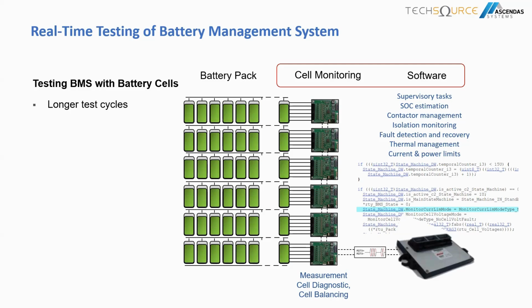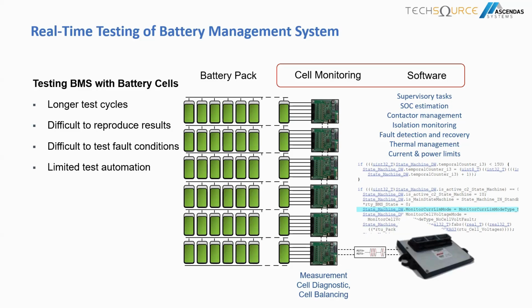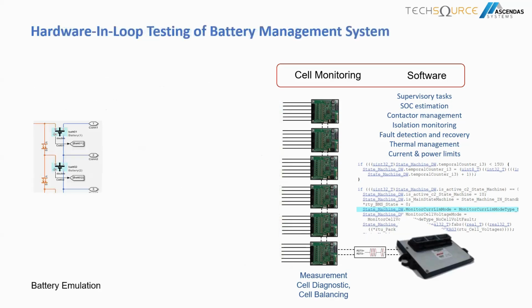These are just some examples, because it's difficult to do testing with actual battery systems. Especially for fault diagnostics, we usually use real-time systems to develop our implementation. One example of a real-time system is Speedgoat hardware, a platform where you can execute large-scale battery pack models with high-frequency dynamics, for example sensor emulation and fault insertion.